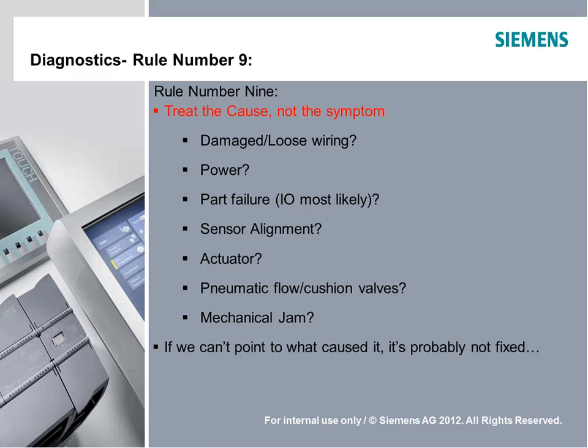So once again, damaged or loose wiring is at the top of the list of culprits when we're going to see problems that can be intermittent or just obvious. Sometimes, the feedback we got from our first diagnostic webinar was, just look at the machine. Oftentimes it's really simple. There may be a plug just unplugged from a solenoid valve dangling under the machine, and that's all it was. So a good survey of the entire machine before you do anything else makes sense.